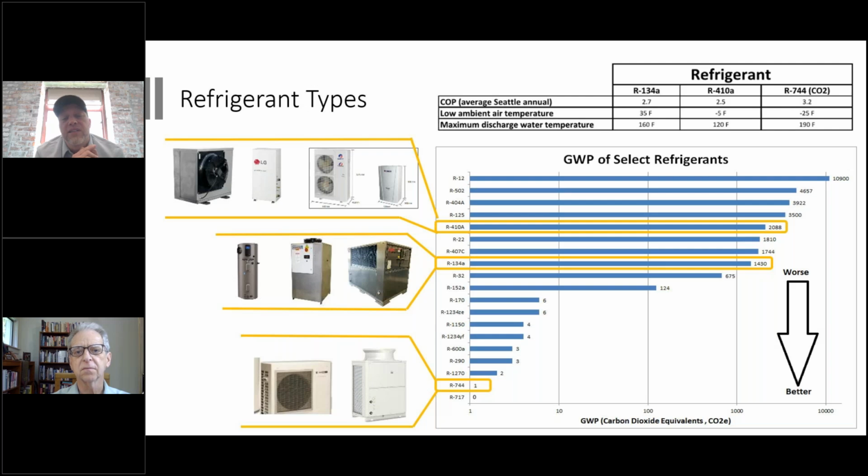The replacement or the transition refrigerant is after that. Sorry, I'm drawing a blank, but the 513, I think that's shown there. But the next generation, replacing the 134A, has pretty similar operating characteristics. Then we've got 410A. 410A is generally good for cold, but not very hot water. So it's sort of the opposite problem. And that's traditionally what's been out there.